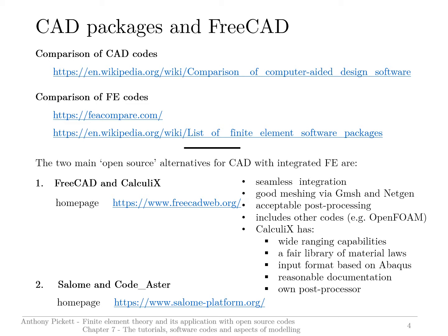There's good meshing capabilities via two open source meshers that have been integrated, called Gmsh and NetGen. The post-processing is not great, and as I mentioned on the previous slide, sometimes it's better to use the Calculix post-processor CGX. There are links to other software, in particular OpenFOAM.